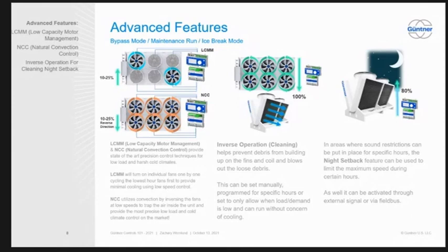That was going to be my question, where basically I was thinking that it was almost like an economizer, right? Where you're sending out a voltage to control it. And typically on an economizer with VFDs, you have a feedback loop that basically tells you how fast you're actually spinning. So if you're not calling for anything, and yet the thing is running because of the fans coming on, it knows to revert that and slow it down, so it's not moving in the opposite direction, actually moving air across the coil, correct? Mm-hmm. Which makes for better control, obviously. Yeah.